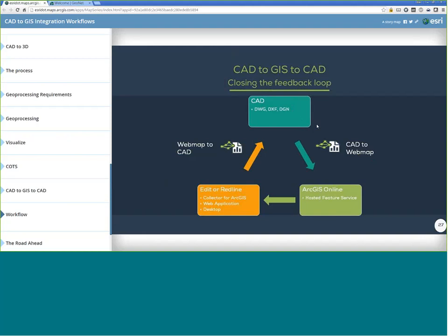And then I've got this template MXD that I merged the file geodatabase to. So I add that file geodatabase I imported from CAD to this MXD, and I create a web map. And all the colors are preserved exactly the way they came from CAD. So I've got layer files set up so that everything matches what it looks like in CAD. And then this creates a web map that I then publish in an automated workflow to ArcGIS Online. So once it's in ArcGIS Online, I have a hosted feature service along with a web map of that CAD file. And that looks something like this.